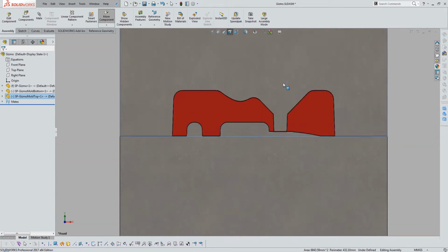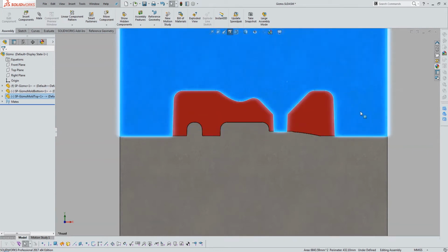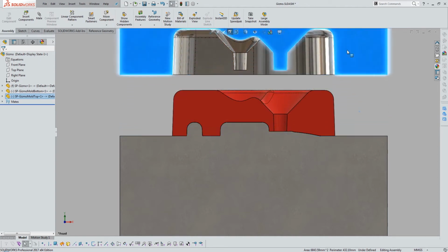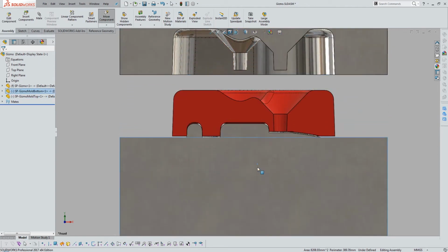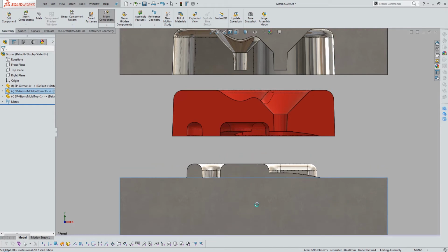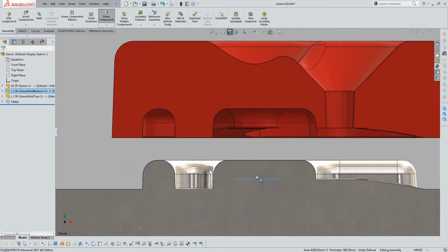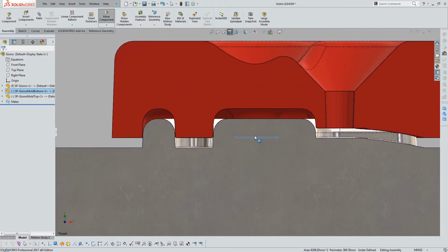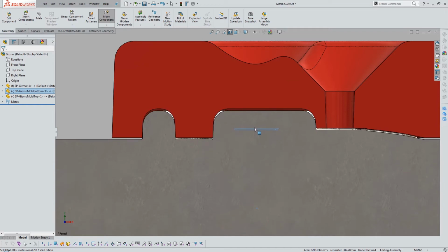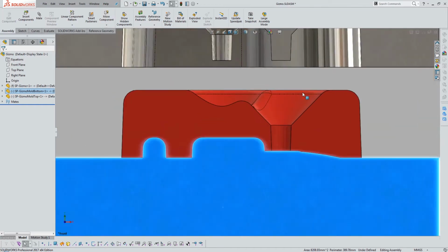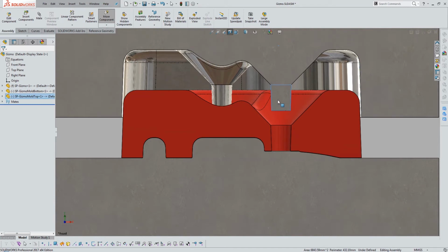When I talk about a direction of pull, I mean this is the top part of the tool and it's pulled off in this direction, and this is the bottom part of the tool and it's pulled off in this direction, and so everything is getting narrower as the tool gets deeper. That's our way of guaranteeing that the tool doesn't get stuck.